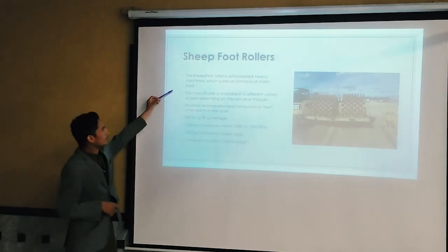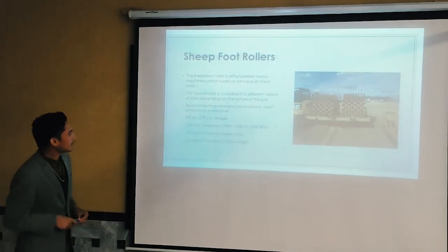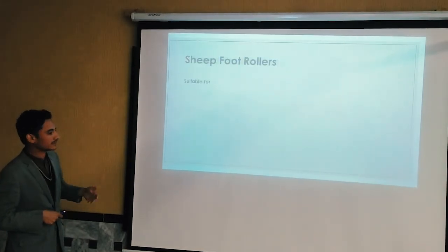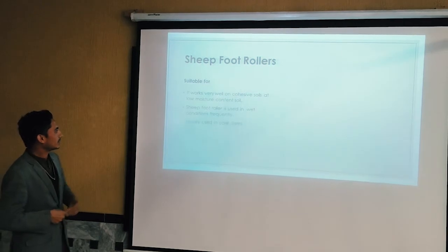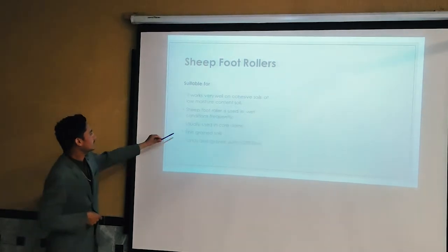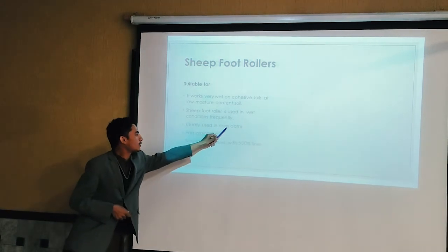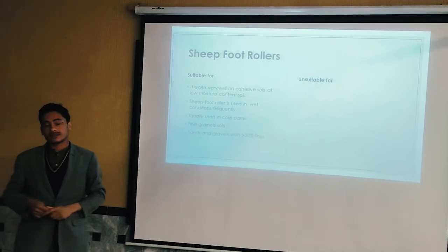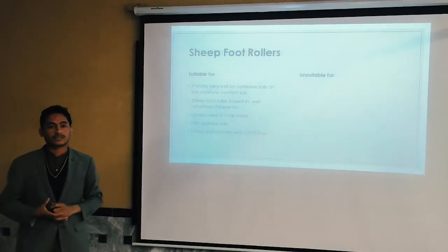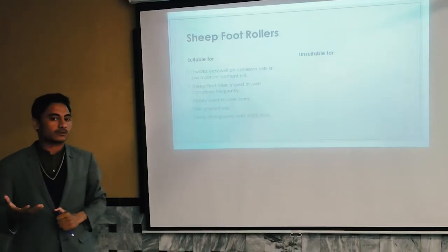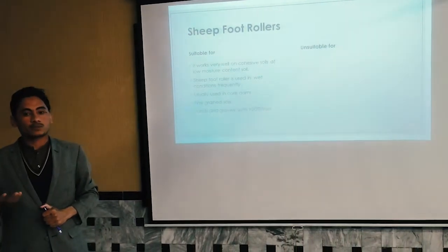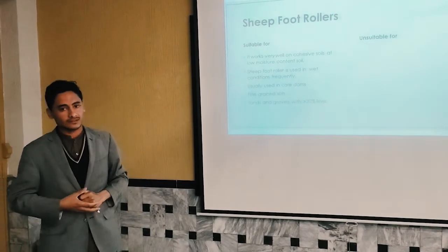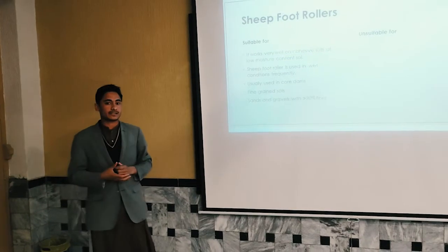There are a lot of points we can say, but this one is usually used in earth dams. And as I told you before, the pneumatic roller is a type of roller that is not suitable. It does not work very well in moisture, when the moisture content in the soil is more.